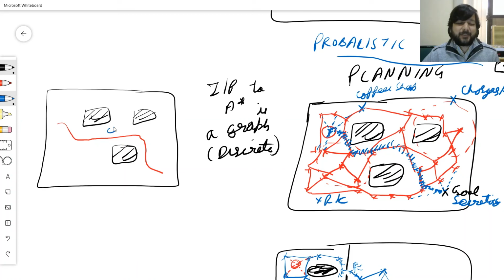Now we say that, okay, many people come in, so it will break this into sub goals. So let us say the last point visible is the sub goal. And as the robot goes around over here, that's my robot. So using potential field, it avoids these people. It goes here. That's still the sub goal. It goes here. It's still the sub goal.